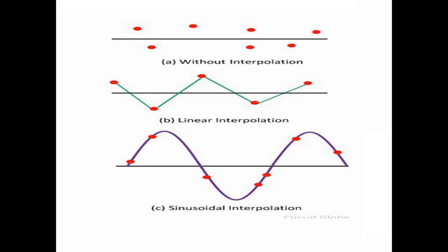Okay, and from the memory we will apply the data to the vertical deflection plates. While applying it on the vertical deflection plates, the display will be just like dots, so we do not get any real form of the signal. To get the real signals, we have to use the interpolation technique. In the CROs we are using two techniques, linear interpolation and sinusoidal interpolation.